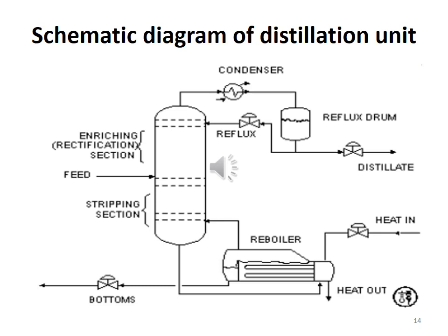There is a condenser which is used to condense the high energy components which are in the state of vapors. They are condensed and transformed from the gaseous state into the liquid state. Then these condensed liquids will be brought to the reflux drum, where the flow is segregated into 2 parts.